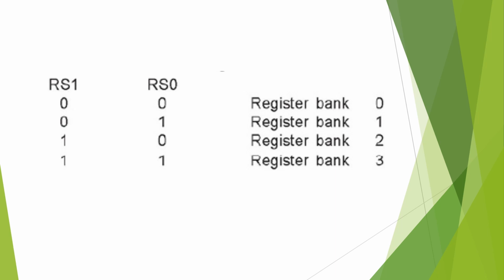Or manually, using the instruction set and clear instruction, we can set or reset the carry flag also. The other functions of auxiliary carry and parity are almost the same as 8085, and there is an extra flag which is the overflow flag. The overflow flag is basically used for signed arithmetic. We have also discussed what signed arithmetic is.